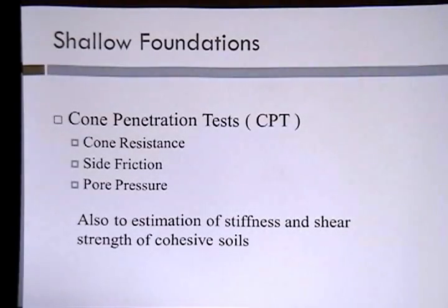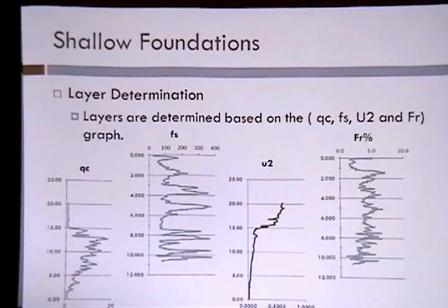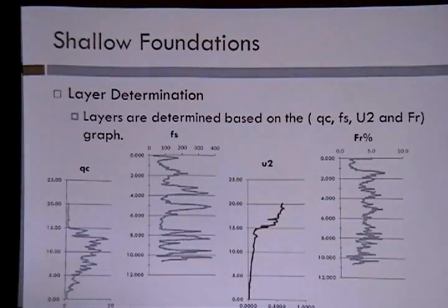After cone tip resistance, sleeve friction, and penetration pore pressure were calculated from the CPT data, the depth of each layer was determined. Layers are determined as shown: cone tip resistance versus depth, sleeve friction versus depth, penetration pore pressure versus depth, and